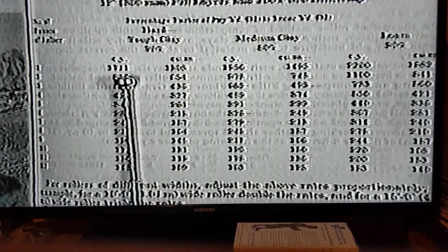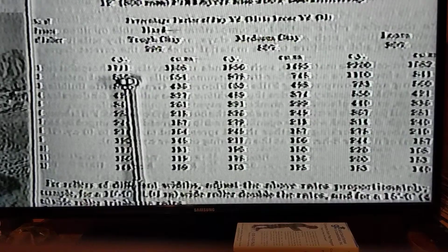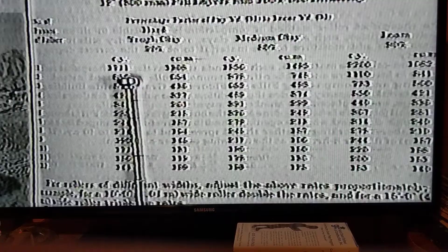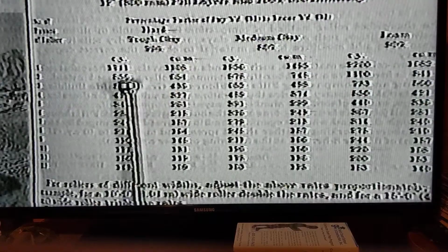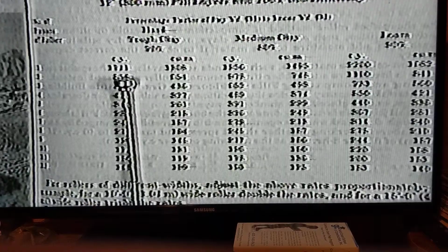Now, what would happen if everything was the same, except that the machine was going twice as fast? Instead of going 2.5 miles an hour, it's going 5 miles an hour. What would you do with this 1711? You would double it. So problems dealing with this table, or tables like it, require that you match the characteristics, find the appropriate number, and then possibly adjust this number for differences between the specifications in the table and the specifications of the question. On the next page, they actually give us an example and then solve it for us, which can serve as a model for our own problems on the exam.